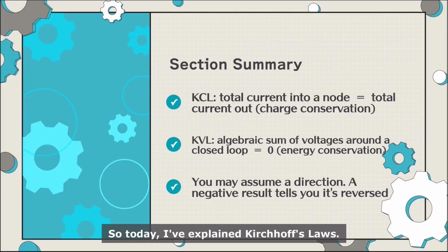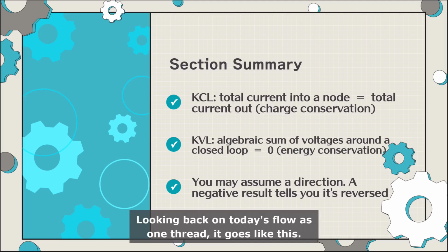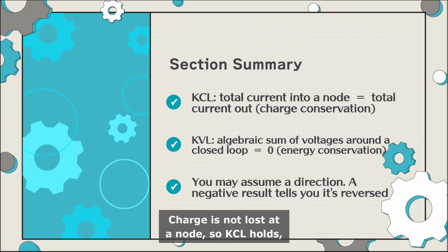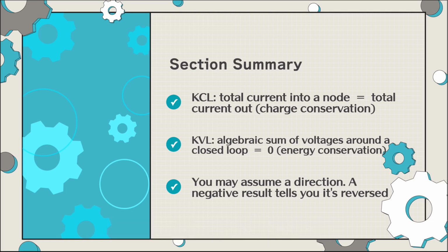So today, I've explained Kirchhoff's laws. Looking back on today's flow as one thread, it goes like this. Charge is not lost at the node, so KCL holds, and you can set up the equation that the total current in equals the total current out.